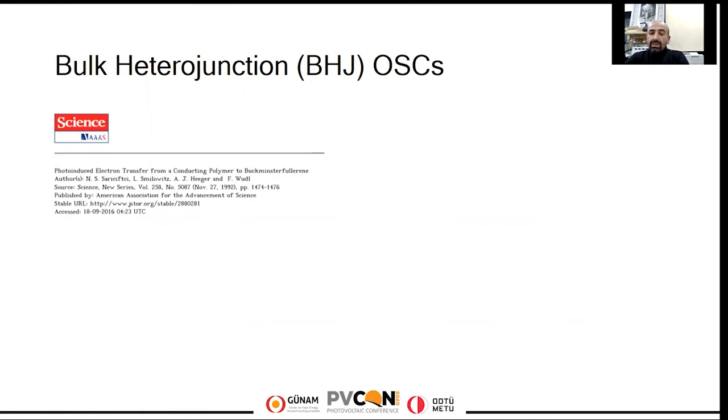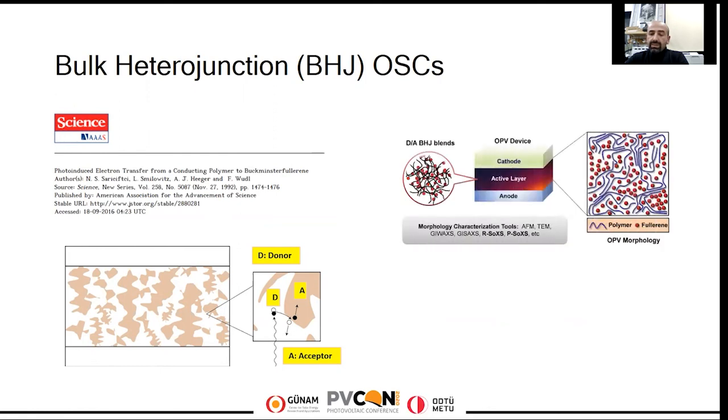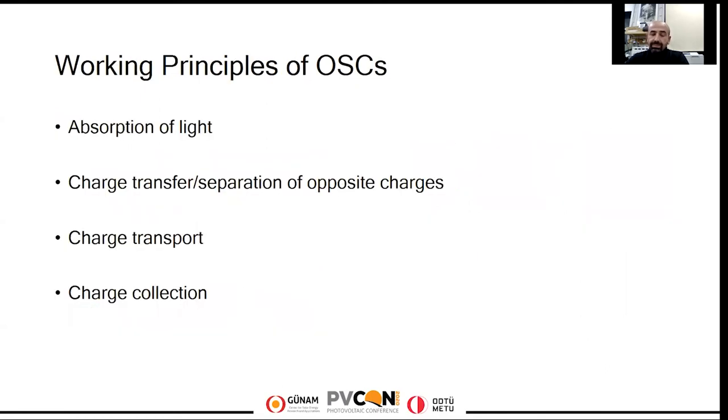Organic solar cells are generally based on bulk heterojunction architecture. It includes an active layer, which is a blend between an electron donor and an electron acceptor. The blend has a penetrating network structure due to self-organized phase separation. Compared to a simple bilayer architecture, the bulk heterojunction geometry provides a greater total surface area for charge separation and reduced recombination. These advantages result in higher power conversion efficiencies.